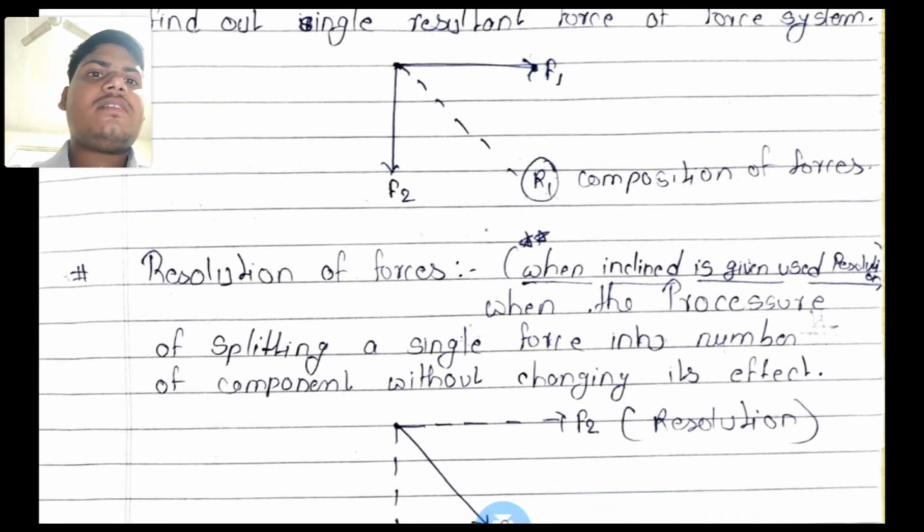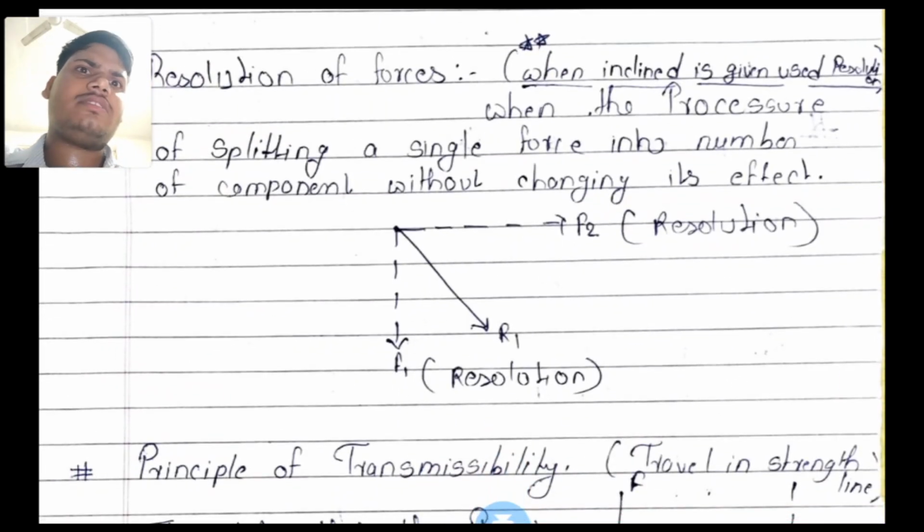Okay. Now resolution of force. If we understand it in a simple way, when an incline is given, use resolution. It means the procedure of splitting a single force into a number of components without changing its effect. A diagram shows resolution of force. This F1 and F2 are the resolutions and R1 is the composition of force.